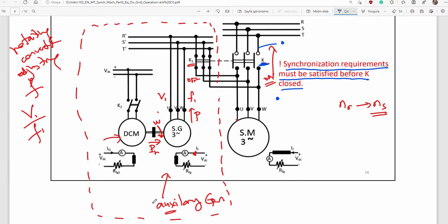For example, that is a rotating auxiliary generator starter. You set up such a starter in a factory, that is the auxiliary bus. Assume that there are lots of synchronous motors in a factory, and you decide to start one, so you choose K1, start it up and then connect to the network.